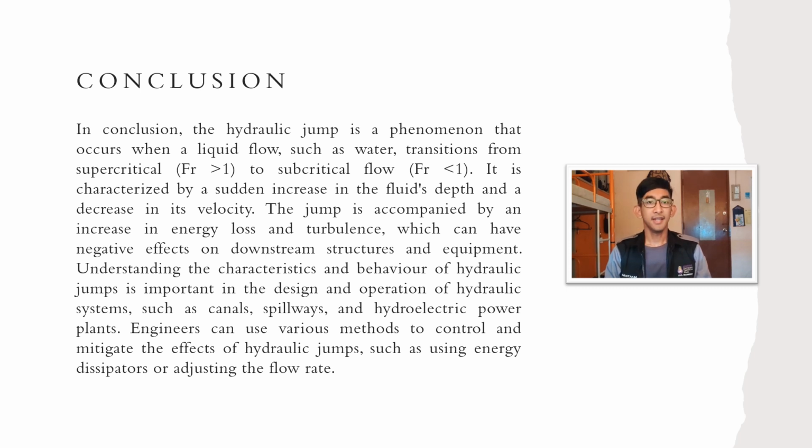Understanding the characteristics and behavior of hydraulic jump is important in the design and operation of hydraulic systems, such as canals, spillways, and hydroelectric power plants. Engineers can use various methods to control and mitigate the effects of hydraulic jumps, such as using energy dissipators or adjusting the flow rates. That's all from me. Thank you.